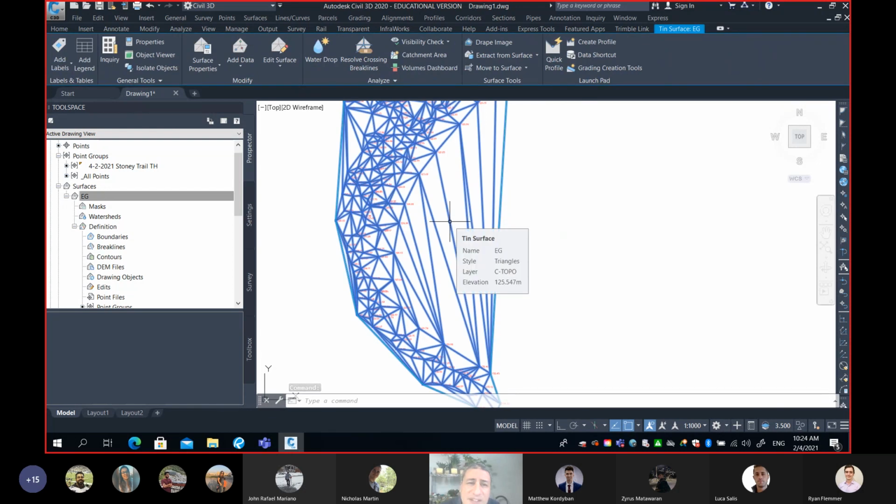So what you see here is a very nice feature of Civil 3D. It has something called a contextual ribbon. Once you click on any element in Civil 3D, Civil 3D is smart and will think you are probably trying to modify that element. So it simply shows you all the commands that you can apply to this element.